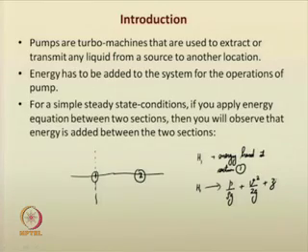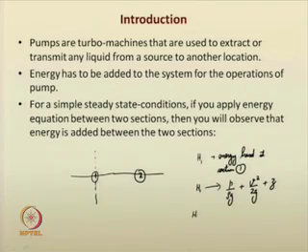So, if the energy at this particular portion is given, similarly at section 2 you can write the energy head appropriately. Of course, if the flow is occurring from left to right, there could be some natural energy losses. If you take that also into account, that is fine.